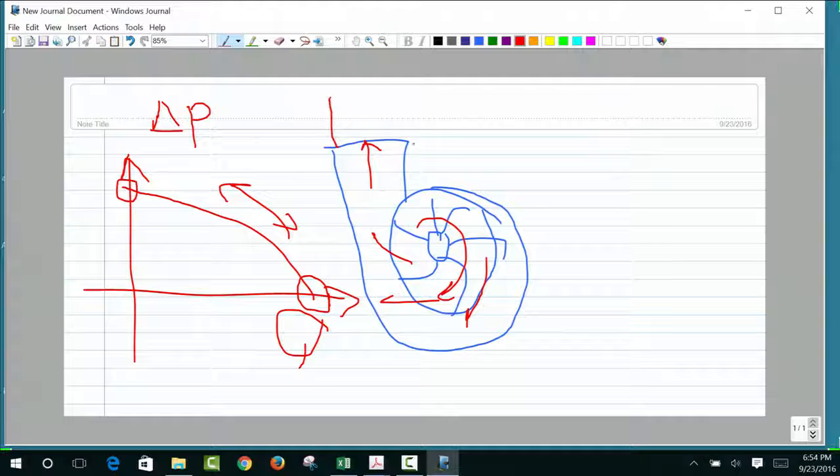That is typically determined by the system here, a long pipeline. The longer this pipeline, the more the load curve would be like this. As you increase the friction or the length, you move this way, and the pump, rather than running here, will be running there. So you get lower and lower flow rate, but higher and higher pressure.